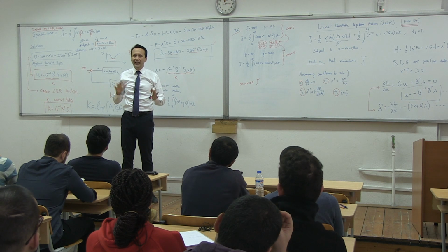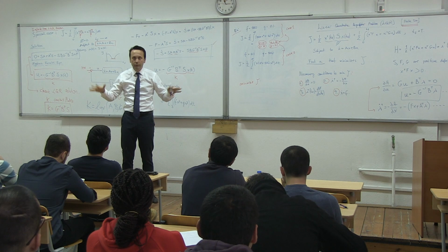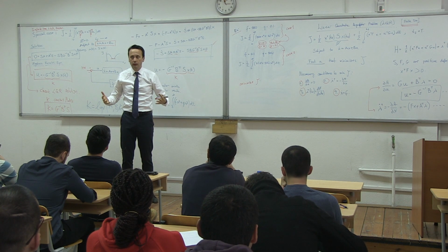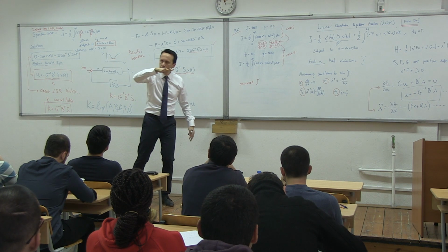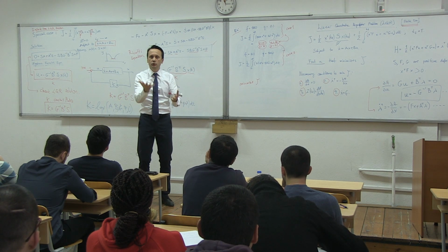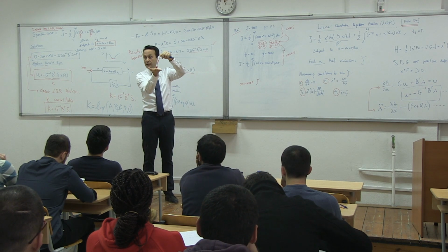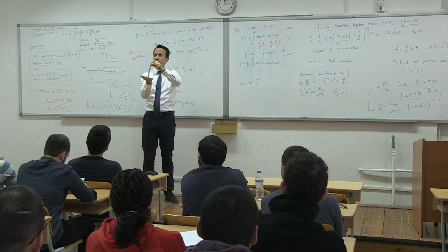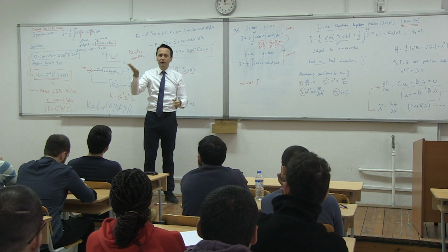But if you give a lot of authority to the controls, which means the controls are moving too much, basically the autopilot is working a lot, then you can actually make a very unstable aircraft very stable. But the controls are moving too much. Okay? So you give the choice. A good example is this one here. This is an unstable thing, right? This is like an inverted pendulum. If I work very hard, I can stabilize this. So if I work very hard. If I'm lazy, it will fall down.